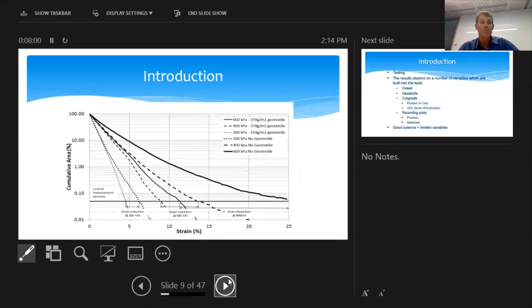If we graph this somewhat differently, what you can see is where we've done the comparison here between a geomembrane with no protection at 600 kPa confining pressures with strains exceeding 25%. You include, again, a lightweight geotextile into that mix, and it significantly reduces the strain values developed down to around the 12% mark. Now that's a big difference.